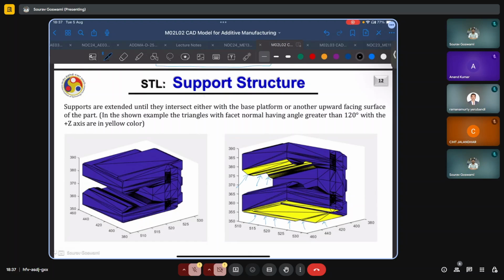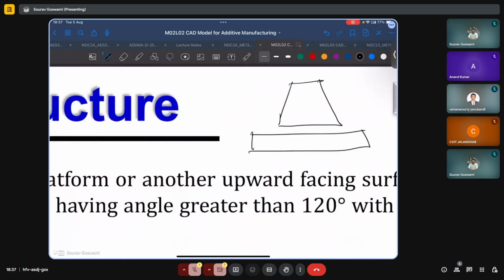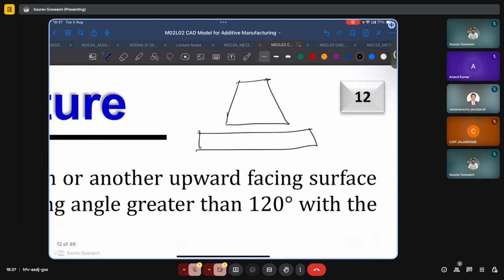So typically you will be building on a substrate plate or a build plate, and whatever your geometry, often in processes like powder bed fusion or FDM, we would need to remove it from the build plate, and we would just have some weak supports here, which can give you the necessary machining allowance, as well as can preserve the geometry of your part and can prevent damage to the build plate itself.